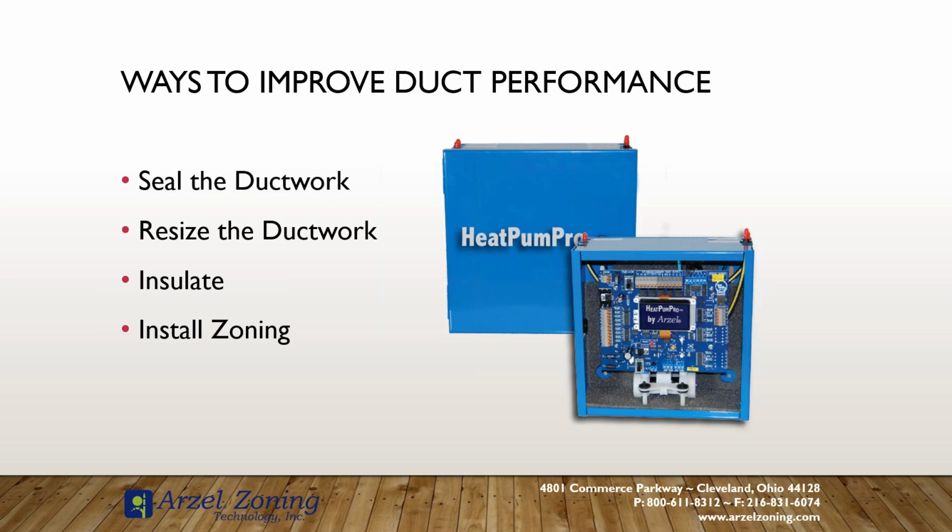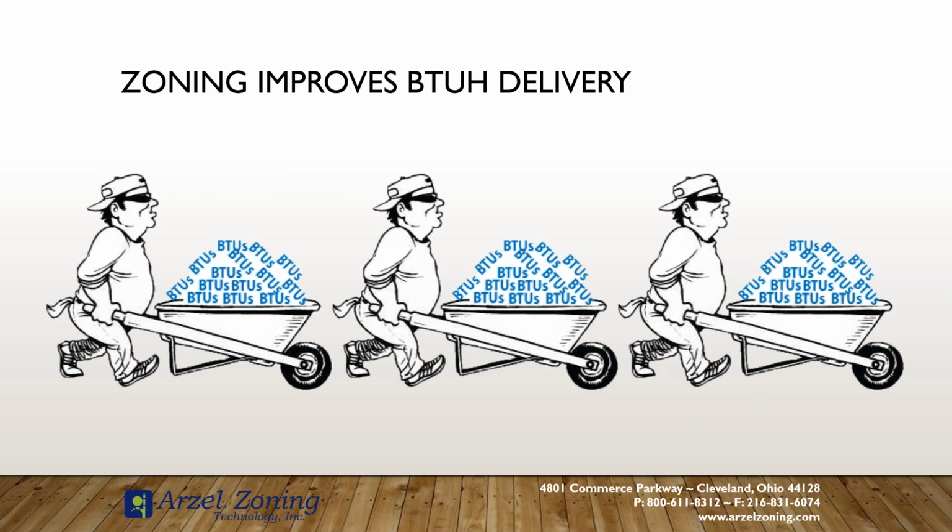So sealing ductwork, resizing ductwork, insulating, installing zoning. And being that we're a zoning company, I'm really here to focus on the zoning side of things. But our zoning increases our velocity, and some velocity increase is a good thing, as long as we're not pushing it so high that we can damage our equipment.